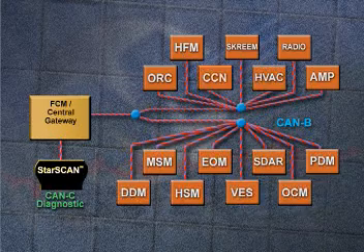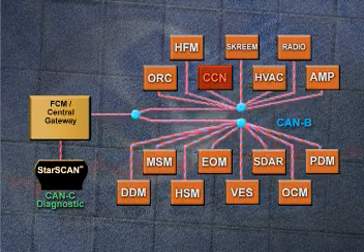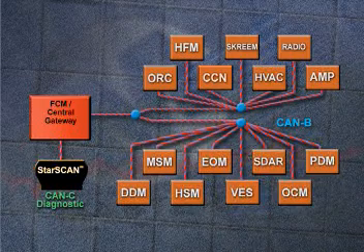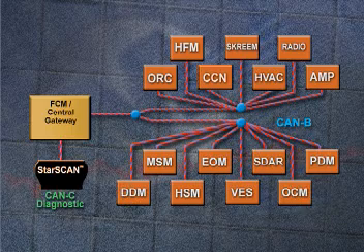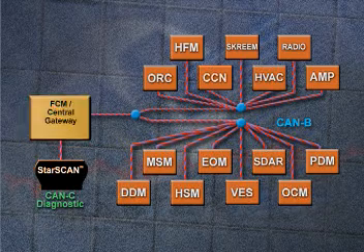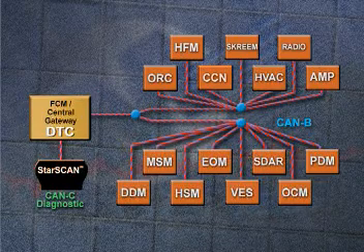Earlier, we briefly mentioned that when a malfunction occurs, the central gateway is responsible for communicating the trouble. This can take different forms. For one thing, modules relay trouble codes of all kinds to the star scan through the central gateway. If these trouble codes concern the bus, they will be preceded by the letter U. The central gateway also monitors the bus for malfunctions and will store trouble codes when it detects them.